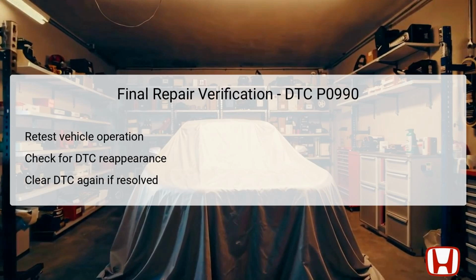After completing the necessary repairs related to DTC P0990, it is crucial to verify the effectiveness of the repair. Begin by retesting vehicle operation to ensure that it is functioning as intended, particularly the shifting capabilities across all gears. During this process, observe whether the vehicle can now shift into all intended gears without restriction. It is also vital to check for the reappearance of the diagnostic trouble code.